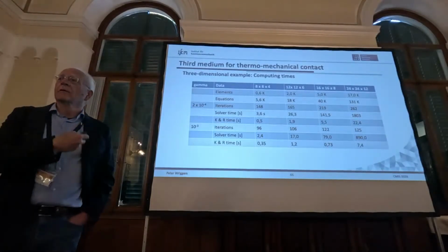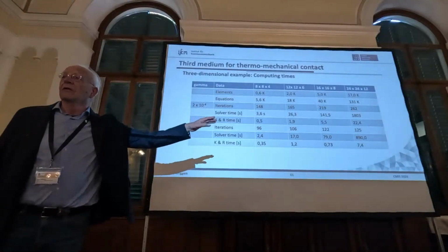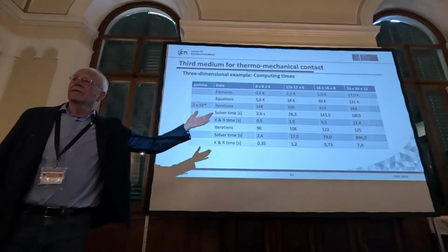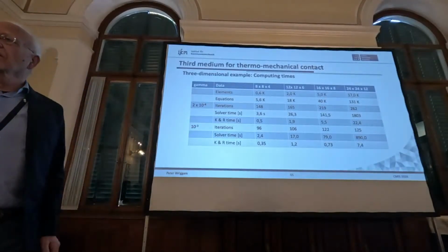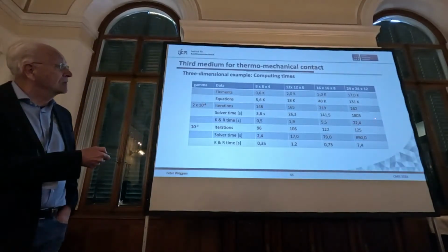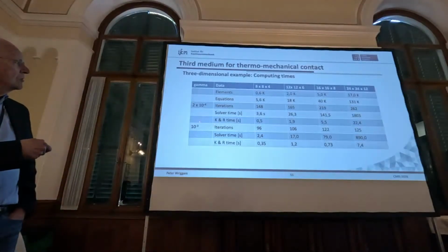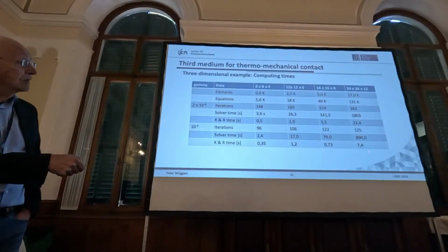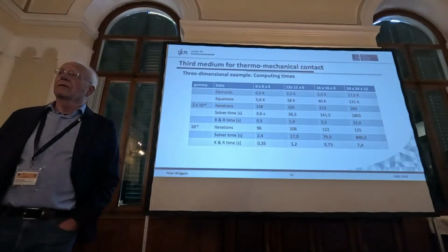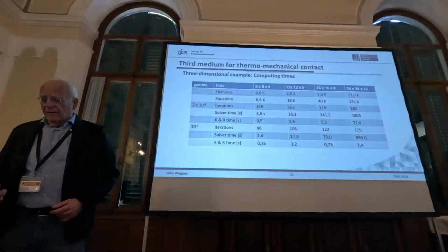So, I mean, if you then have a good solver, you can, of course, improve this. I use Pardiso, which is not bad, but for these type of problems, I think it's better to have some nice solver, which has an AMG or whatever inside, which I don't have. And of course, if we reduce the gamma, then we also reduce the number of iterations, and of course, then you also reduce the time to solve them. But I just wanted to say that.